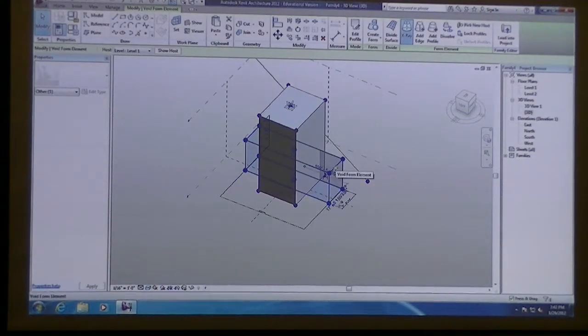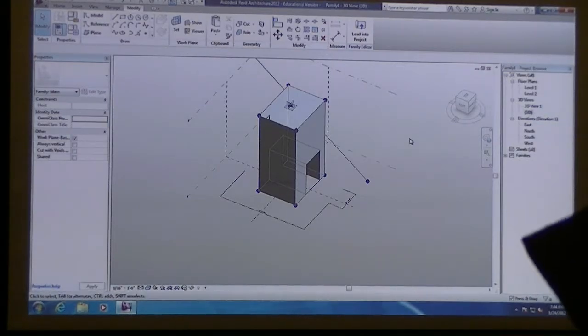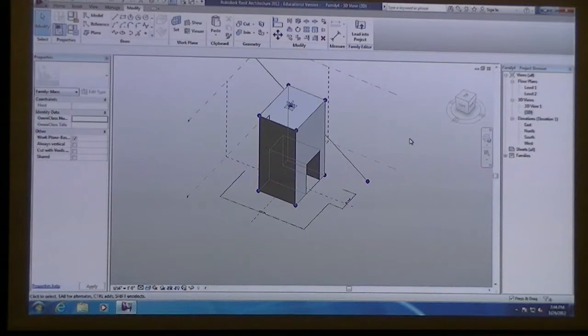So that's why I like to set up the solid first, because once it's a void, it loses a lot of its other properties. But what that would be used for is if you're looking at my model, you can see I've got these curved walls on either end of the bridge, and then I've got a little notch that was coming down to hold in the actual placement of this one part of the bridge to the other. So I might actually create this as an extrusion and then have another parametric void that's associated with this curve that could cut out this notch for this element.